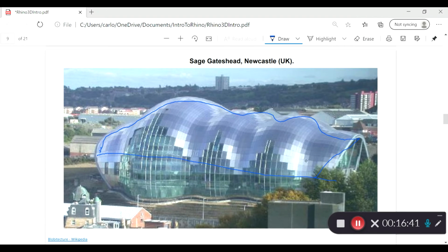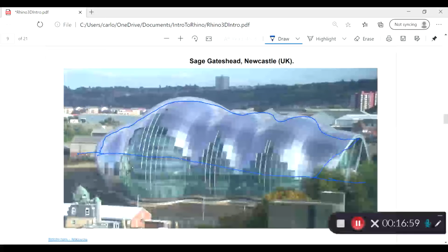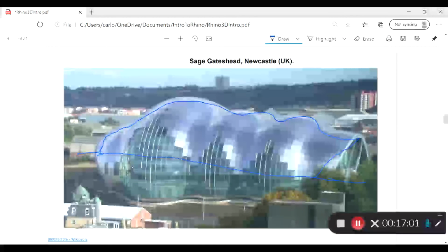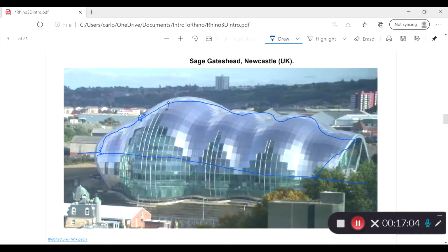If you were to revolve this, and we'll go through this when we open Rhino and get to revolutions, when you create an axis and you revolve this part, you can create that shape very close to this shape. Of course, you would later go and pick some points and adjust them and so on and so forth. But from the Rhino perspective, it is not very difficult to build.